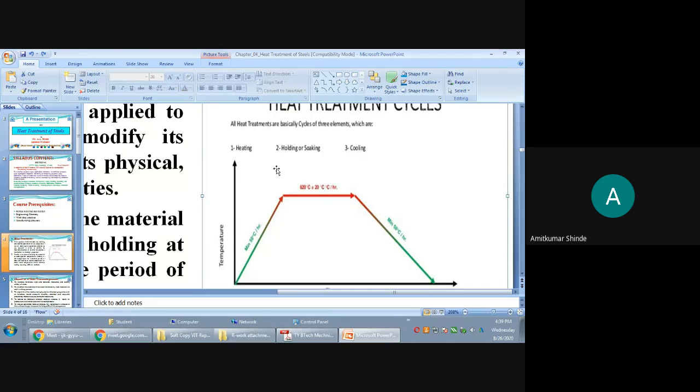But you have to remember here, whichever structure you obtain, if fast heating is not performed, you will end up with a coarse structure at that higher temperature, and due to this you will end up with a coarse structure at the end also, and due to that, its mechanical properties like tensile strength and hardness will be very low. Whichever required properties are there will not be achieved.